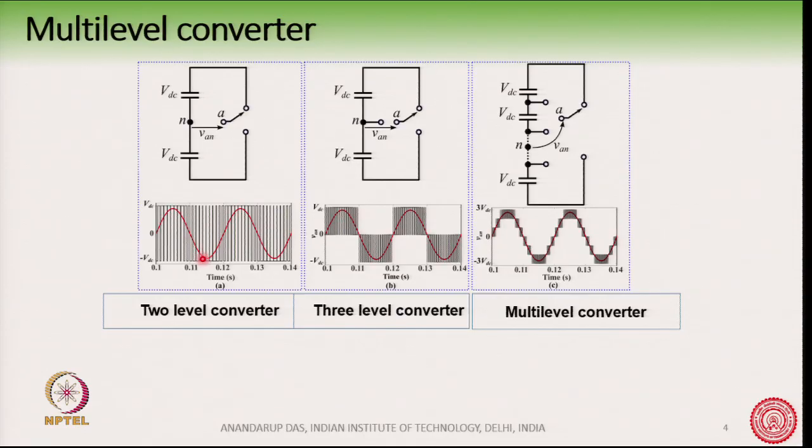Here the harmonics produced at the pole voltage waveform are more as compared to here. So, this waveform has a better harmonic performance. So, the 3 level converter waveform has a better harmonic performance than a 2 level converter waveform, simply because of the reason that is evident from the waveform that the instantaneous error is less.